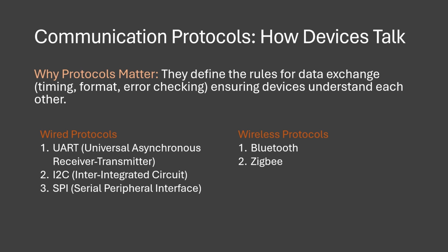If you have enough power on the circuit to power that particular mode of protocol or not. So also you have to look at the complexity. How complex is it for you to set up? Sometimes it might be difficult to set up Zigbee compared to Bluetooth. And sometimes it might also be difficult to set up SPI compared to I2C. So you have to look at all these protocols and look at the one that will give you the best return or that make things much easier for you.